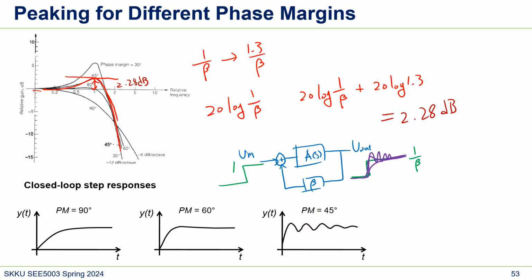So that's why in a previous slide, what we said as a rule of thumb is phase margin of like 60. So this is a good thing. But the other thing we can think about is, is large phase margin always good? No. If you have large phase margin, it's slow. So this is faster. It means that if we have too much phase margin, then it can be slow. I mean, the step response is slow.